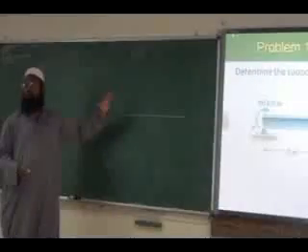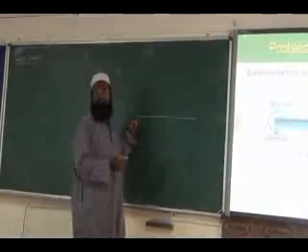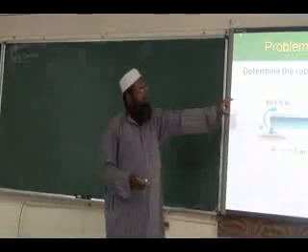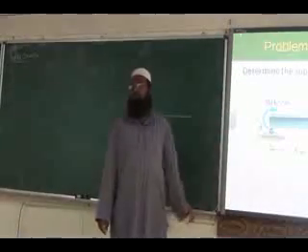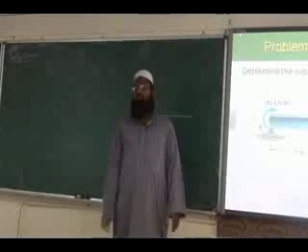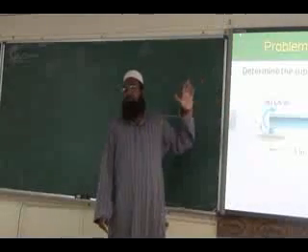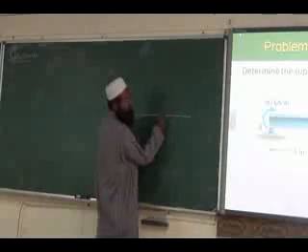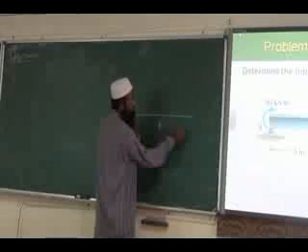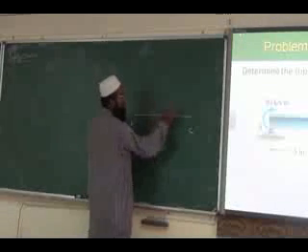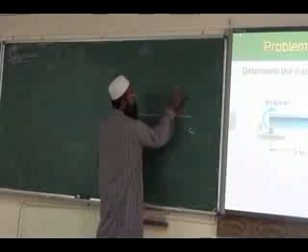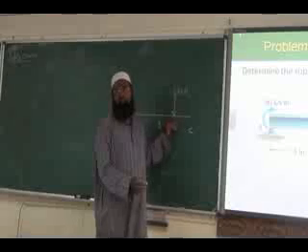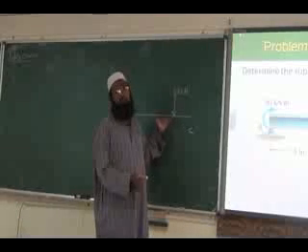This is the given beam, line diagram of the beam. So first we convert UDL into a point load. The magnitude of UDL is 5 kN per meter. It is over the length of 5 meters. So 5 times 5, 25 kN will be acting at the midpoint of portion BC. So B is here, C is here, A is here. So we will have 25 kN acting at the midpoint. So this is your UDL. UDL is now converted into a point load.